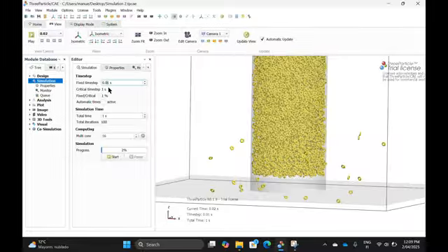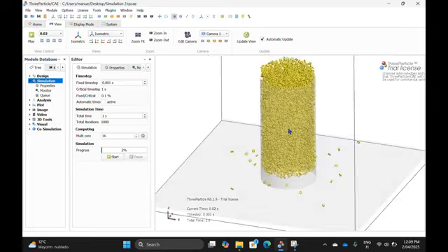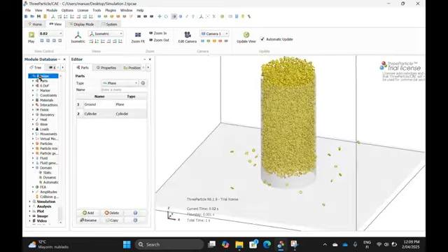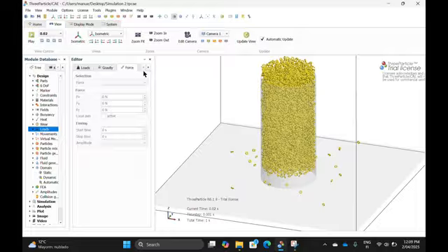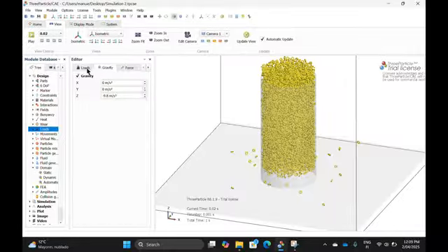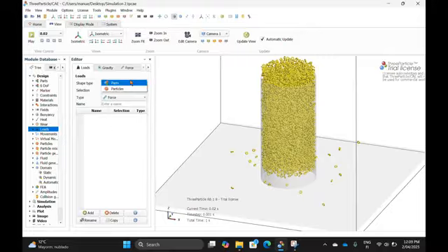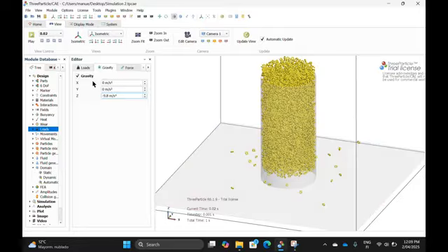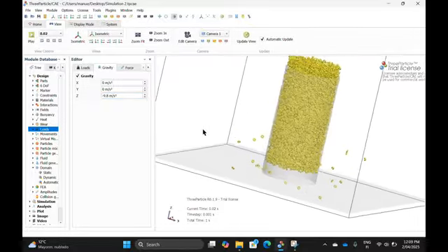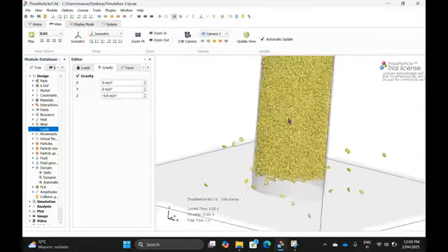Yeah, we need interaction between bulk and steel, and between bulk and bulk, of course. We need between bulk and flexi. That's it, right? That's it. Everything else is fine so far. Bulk and steel is the first contact to the floor. Restitution of 0.1, donuts are quite soft, right? Static friction higher, I would say 0.5, 0.4. Bulk, I would say, ooh, this is even more soft, 0.01.